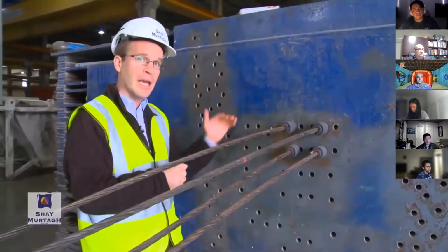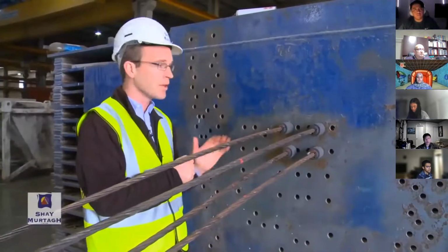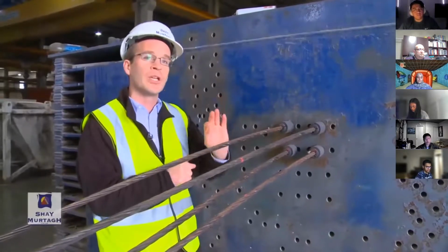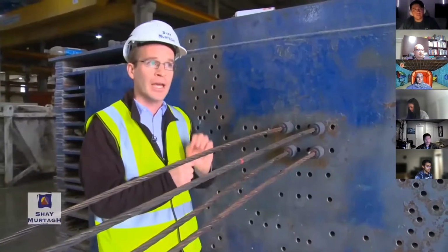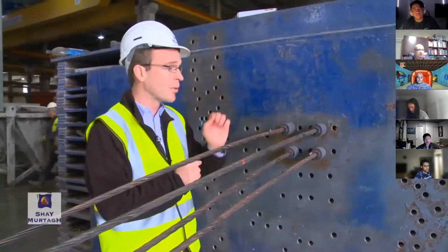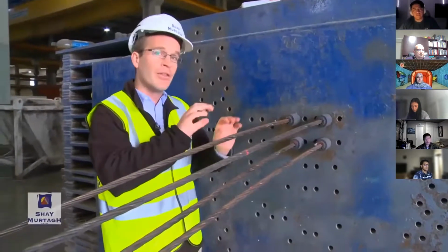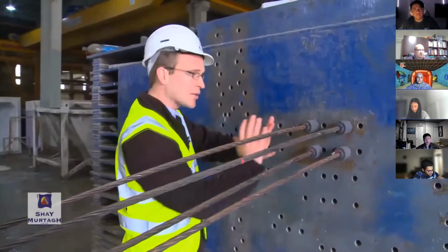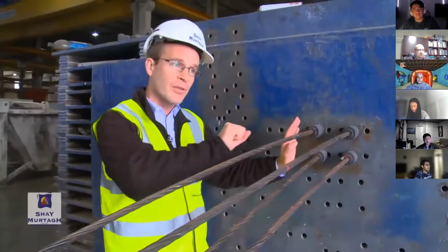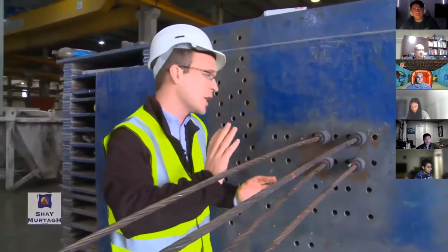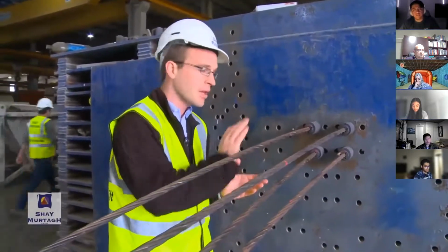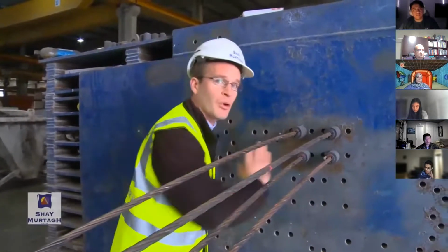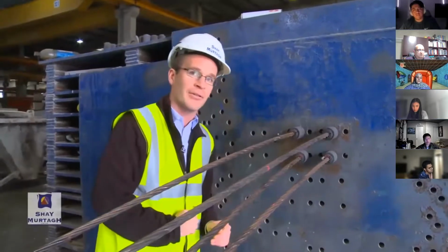The concrete would be cast around the strands into the appropriate cross-section. Once that concrete has reached the specified compressive strength, then the strands would be gradually released, thereby transferring the force that was in the strands when they were stretched into the concrete. So that very large force in the strands would then be applied as compression into the beam itself.